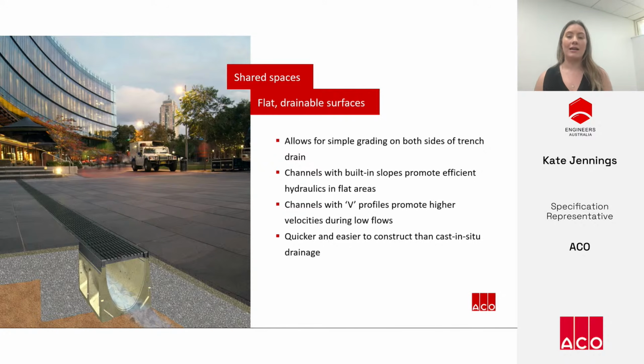As we discussed earlier, precast trench drains with a V-shaped profile have hydraulic advantages over U-shaped channels, in particular during low flows, as the V-shaped profile creates higher velocities within the channel and promotes self-cleansing. Precast trench drainage systems are quick and easy to install, particularly when compared to cast in situ drainage or point drainage.